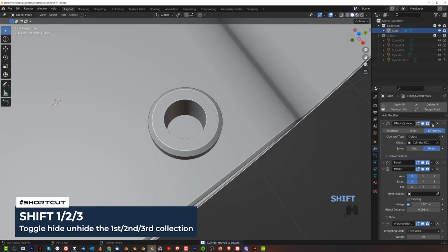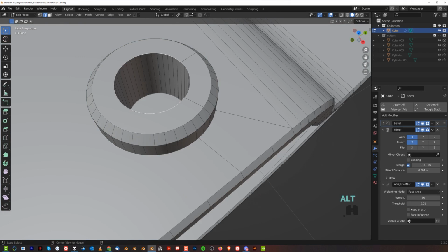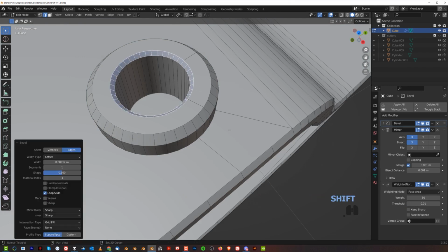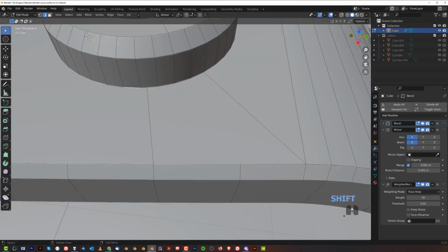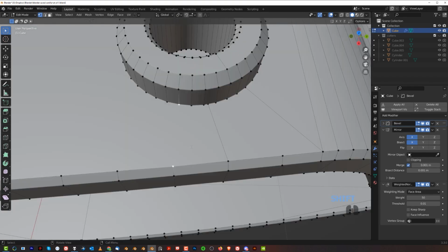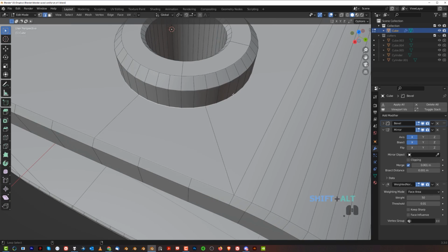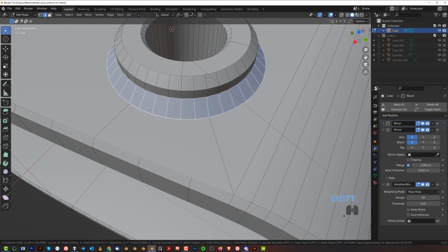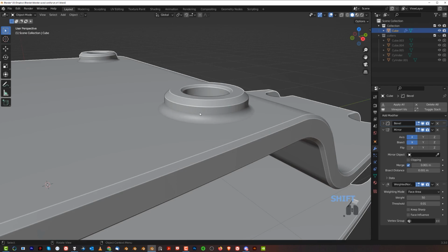Cool, let's apply that because I like this. What we can do here is apply a small chamfer, so click, Alt click, Shift Alt click, Control B, chamfer. And now here I want to create a bevel, okay, around this. Now, when you have edges like this, you want to create more or less perpendicular connections. So here I would rather run an edge like this. I remove this one, this is fine. So Alt click, Shift Alt click, Control B, and then we're going to scroll it like that, okay? Not too many, I think 10 will do. 10 segments. You're gonna have this kind of sort of an imitation of welding here.